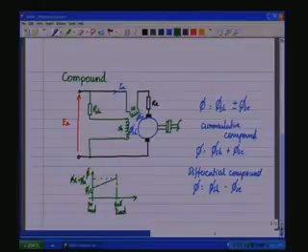So, as the flux increases, you saw that the back EMF is connected across the armature winding, and if you say the back EMF is constant for a given speed, then as the flux increases, the speed will reduce. Which means that as the load is changed from no load to full load, flux is increasing and the speed will reduce.